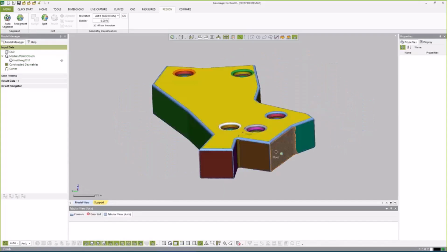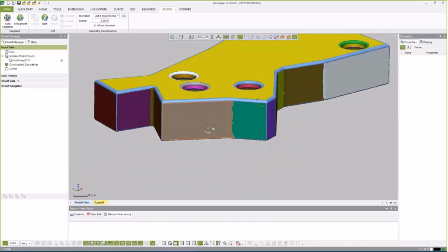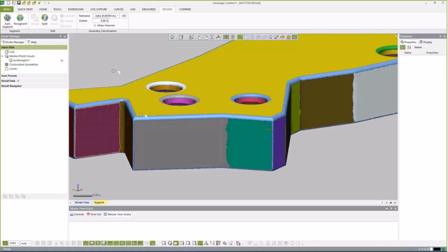So what I'm going to do is find an area where there's a little bit of encroachment. You can see that this plane is actually encroaching into the crease here. So there's a couple different ways we can take care of that. One of the things that we can do is actually just insert a region. What I like to do is draw a line. So I will come in and draw a line here somewhere on the other side of my plane with just my draw tool visible on. And I'll actually just insert a region.